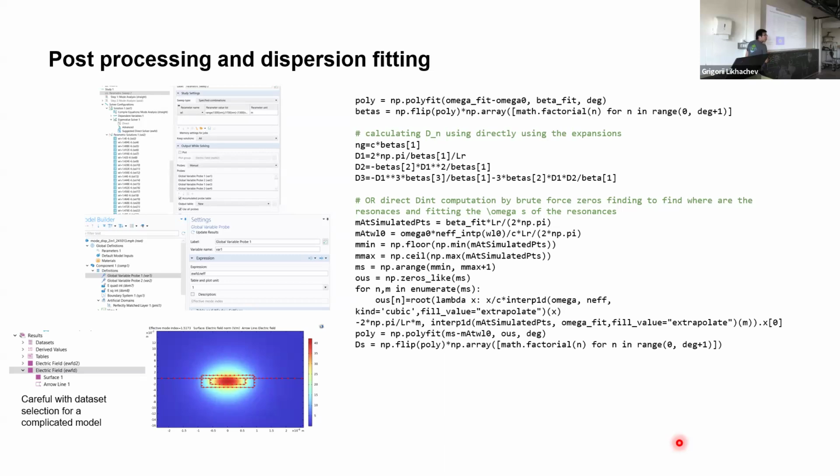But COMSOL doesn't have to, because all the mesh nodes are arbitrarily placed directly on the waveguide geometry you have defined. So you don't need to discretize everything down to 5 nanometer precision. This makes COMSOL converge, I think, much faster, in terms of precision and also memory requirement.